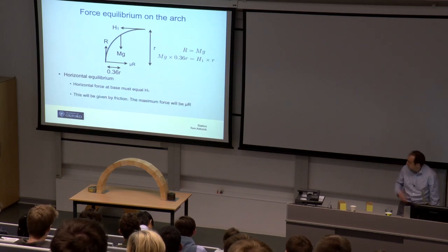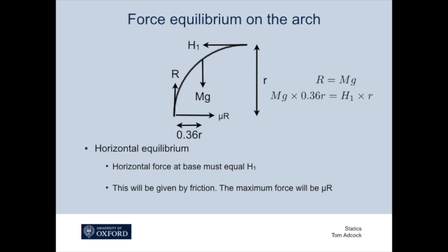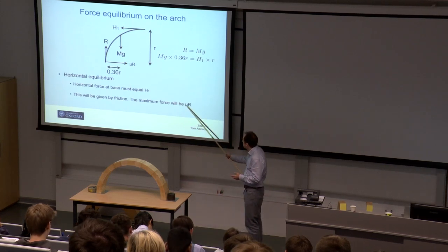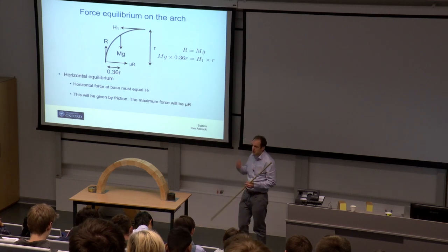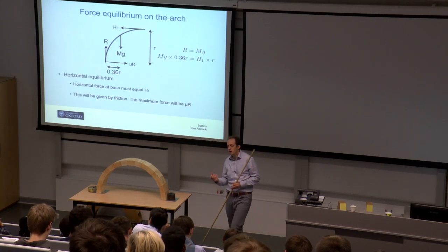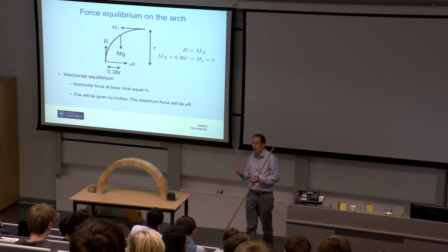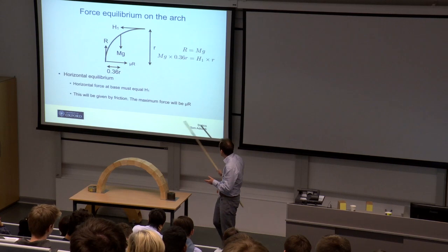Now, most of you will be aware that the way we usually model the frictional force is by saying that it is some proportion of the vertical reaction, what we call Coulomb friction. And we usually say that that proportion is some value which we give the Greek letter mu, where mu is 0 for a completely frictionless problem and 1 for a perfectly frictional problem.